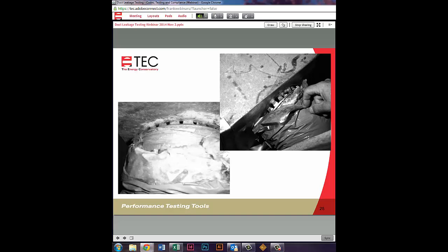Well, invariably, there will be an occasion where there's a 12-foot run of ductwork, but the contractor only has 11.5 feet of duct. And so they will tend to pull on it, and that takeoff, because it's not a very strong mechanical connector, tends to loosen up. So what you see is these holes along the edges, and in the case of the right-hand one, it is nearly completely off. So something that we see quite often.